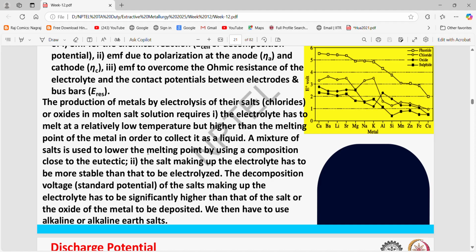Now, if we are talking about the refining of Al2O3 to get Al metal, we require a molten salt electrolysis solution, and we have to work at a temperature of around 800 or 900 degrees Celsius so that this electrolyte solution can melt the Al2O3 and dissolve it in ionic form. Then, by providing current, we can recover the aluminium in metallic form via the electrolytic deposition process.